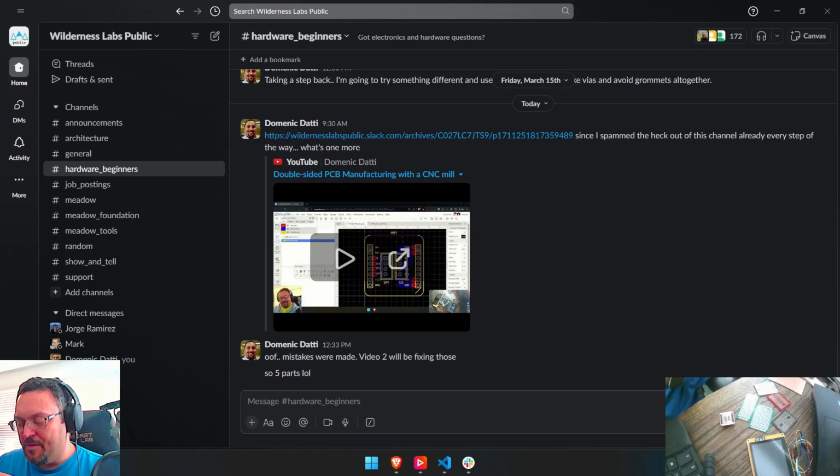That was really important to note, because later on in the CNC milling process, I had said something that wasn't true. I said that it doesn't matter that you do this now, because later on I know that my tool is just 0.5 millimeter anyway, and it's just going to blow through this area. Well, the problem is that FlatCAM knows that too, and it knows the diameter of your tool, and it knows that technically there's only 0.498 millimeters between these two, so your bit is not going to fit between them. So it didn't actually do the geometry to make the bit go between certain areas on the traces that I need it to.